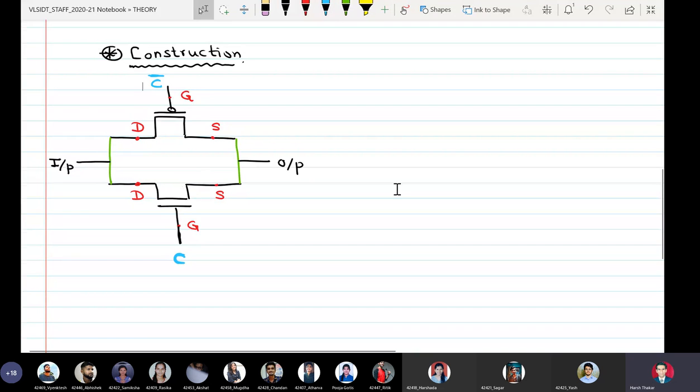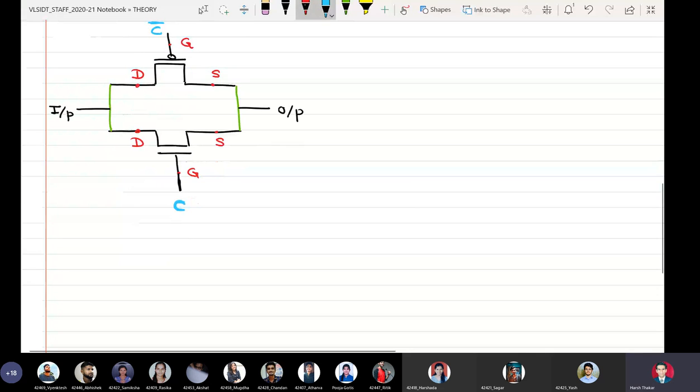So basically C is the control signal, not C bar, but because NMOS and PMOS transistors operate with exactly opposite kinds of logic at their gate terminal, that is why I have to apply C bar to the PMOS gate if I apply C to the NMOS gate. Now naturally we know that this is the control signal, so I purposefully call this C.